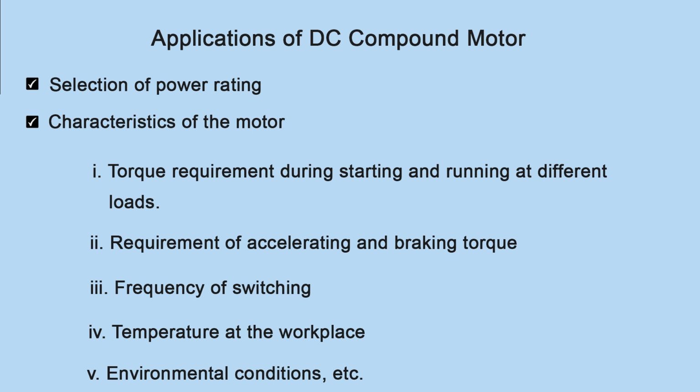Rather, one should know the characteristics of a motor, the behavior of the motor under different load conditions, so that work can be done quickly and efficiently without any breakdown. Therefore, before selection of a motor, one should know the following particulars of the work. The first point is the torque requirement during starting and running at different loads. It is very important for any particular application.